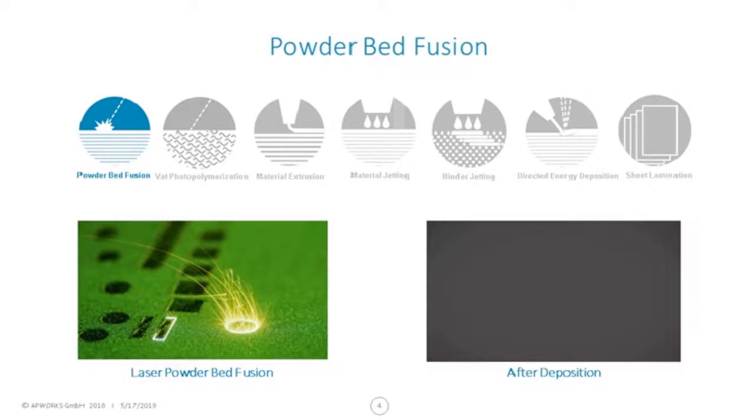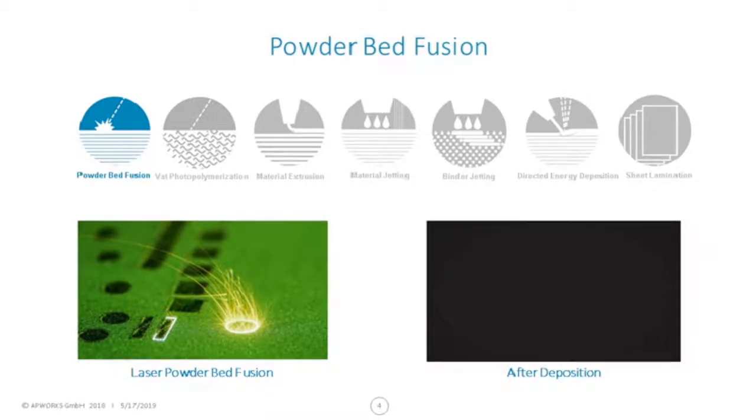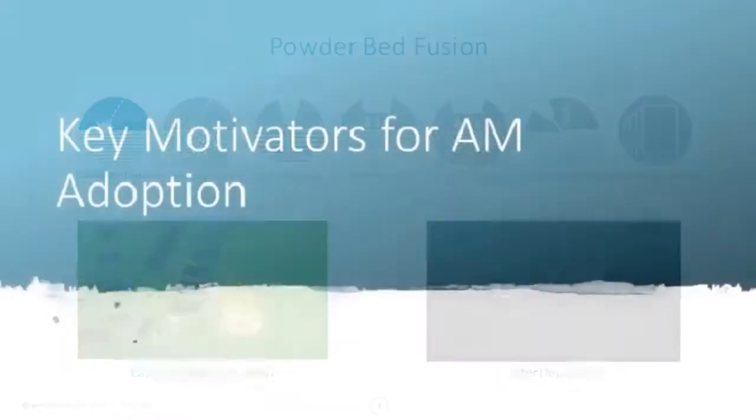So it's quite important to realize that with this type of technology, because you're melting and fusing material, there are residual stresses as a result of the process, and so we have to perform a post-process heat treatment. And in general, there are quite a few post-processing steps required: heat treatment, removal of supporting structures, which are there to minimize the distortion that occurs during the process. So it's not a trivial process to set up, but it doesn't require physical tooling.